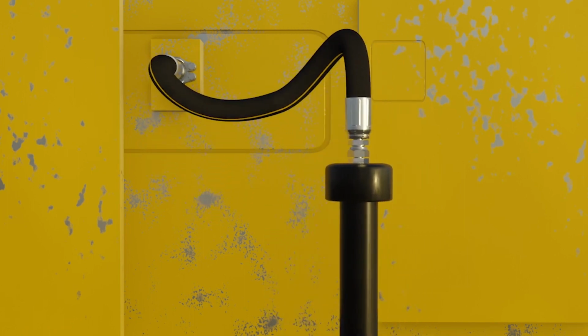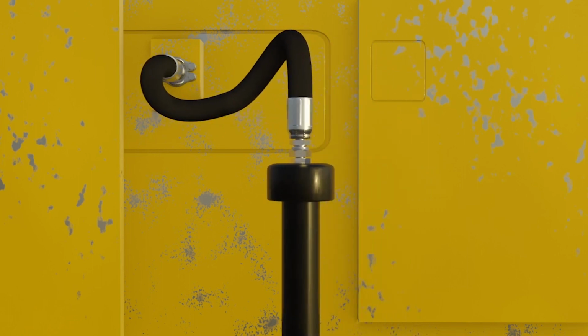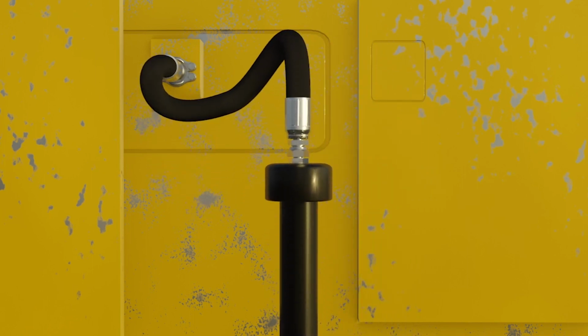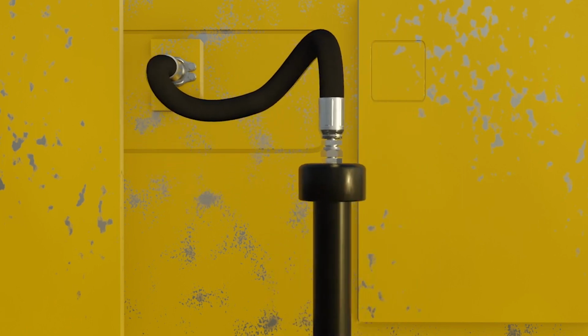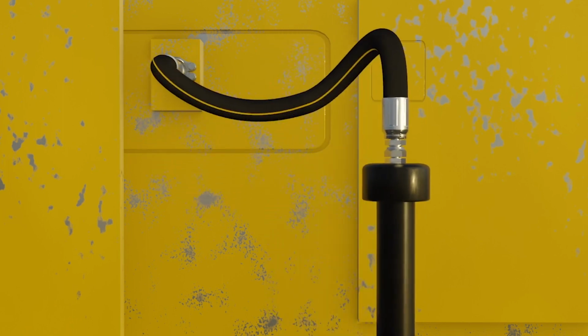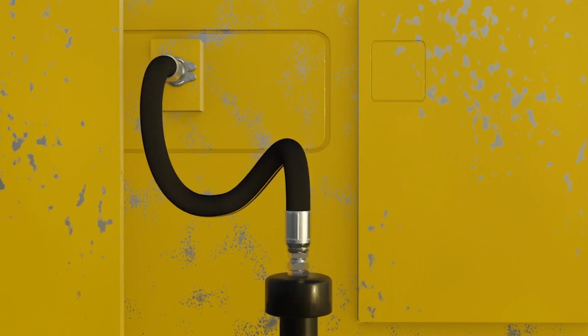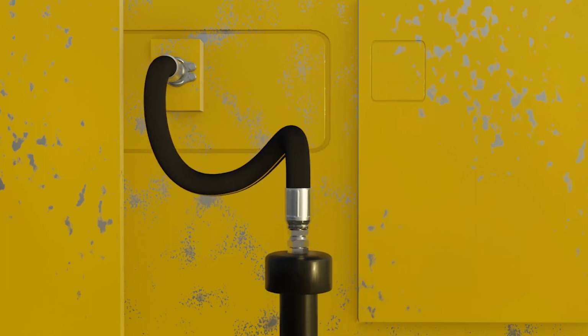Here is one scenario. In the initial position, the hose has no twist. As the left-hand attachment moves towards the right and downwards to the secondary position, a significant twist is forced into the hose. As the element reciprocates back and forth, the reinforcing layers will be adversely affected, allowing the medium to burst through the side wall of the hose.